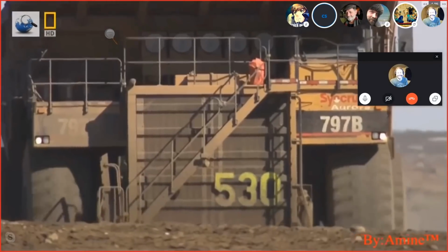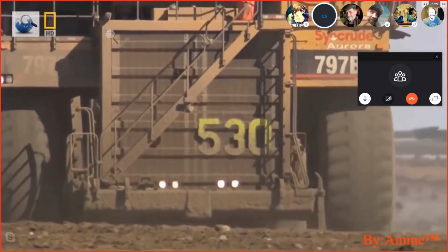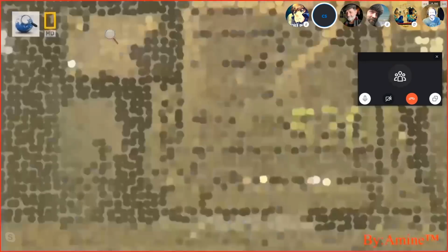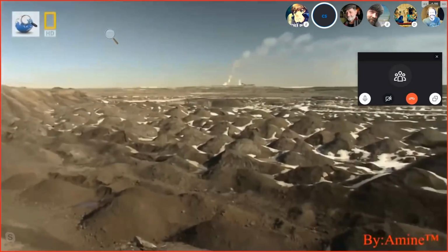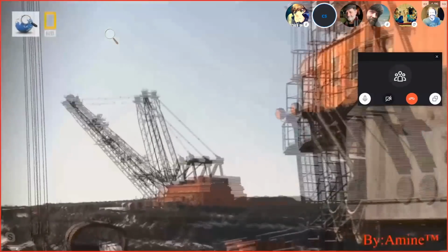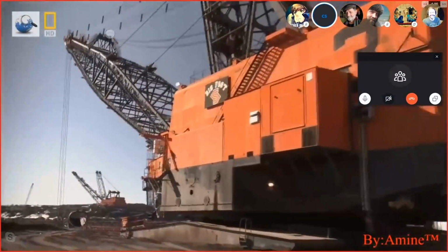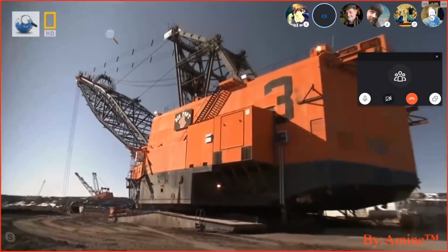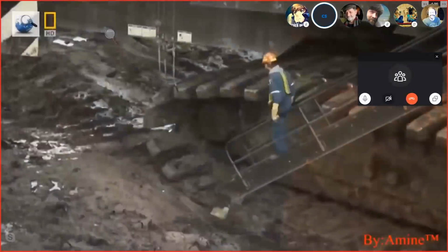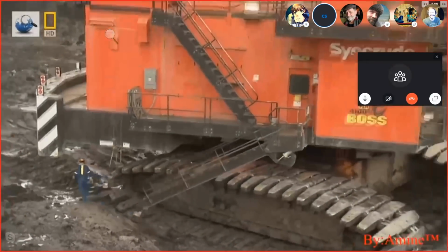Oh. Well, the problem I was called in on was we had a series of 2205 stainless steel tanks. They had half-inch and 3/8-inch stainless steel walls on these things. There was like a half a dozen of these tanks, and they started bleeding this black goo coming out of the welds right around the seams. It just started bleeding this black goo, and it was starting to make actual holes through these tanks. And all they were was really water storage and reagent storage tanks, so mostly just water and some other chemicals in it. And they didn't know what was going on, and this black stuff was coming out through it.